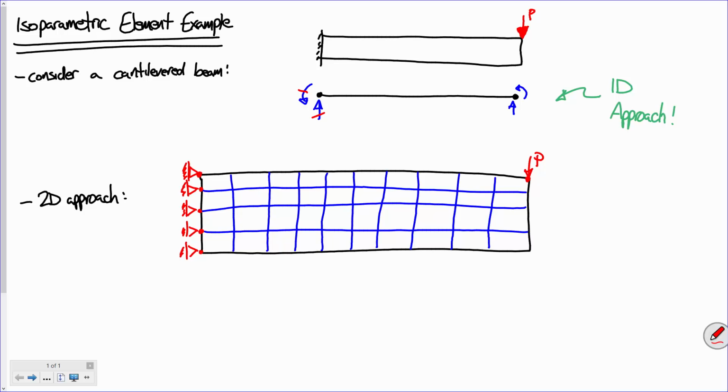Now, is there a purpose for doing that on a problem like this? No, not really. But what if you're trying to find the stresses in an oddly shaped cantilevered retaining wall? Or the stresses in some mechanical planar component where the geometry is really weird. That's where the finite elements comes into play. Now, for the purposes of this example, I'm going to isolate a particular element. Let's say this is the element that I'm after. My goal is to write a K matrix for the shaded element.